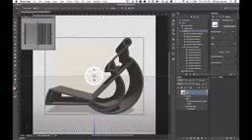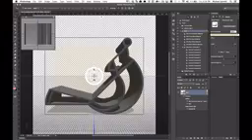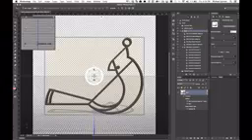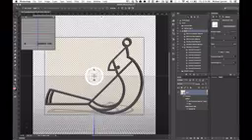Currently it's set at just over 1.5 inches, but I'd like to change that to 1/8 of an inch. Type in the number 0.125 for inches, or 3.175 if you're working in millimeters. As you can see from this change, the 3D model resembles a pendant, one that you might hang from a necklace or a keychain. The last thing I'd like us to do with this object is to rotate it 90